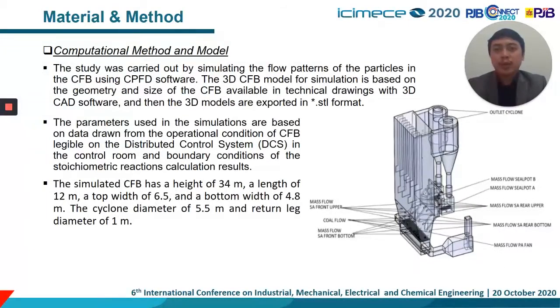I'll move on to my next point, which is the material and method of our research. The first is computational method and model. The study was carried out by simulating the flow patterns of the particles in the CFB using CPFD software. The 3D CFB model for simulation is based on the geometry and size of the CFB available in technical drawings with 3D CAD software. Then the 3D models are exported in .stl format.